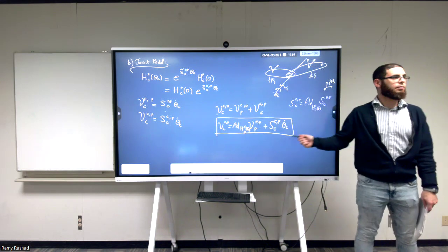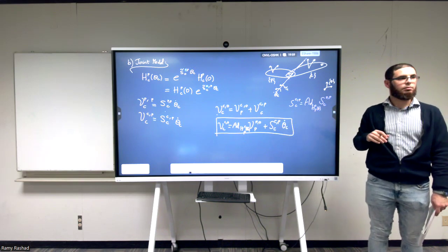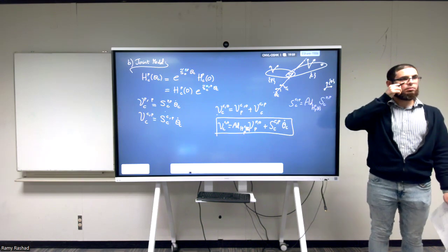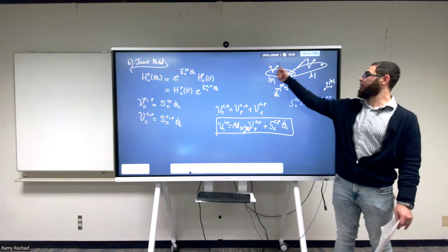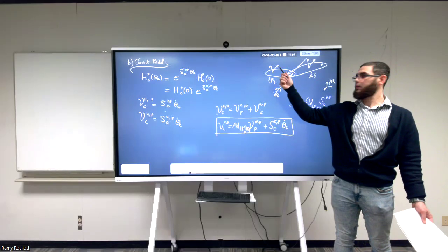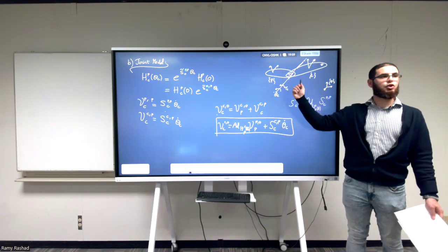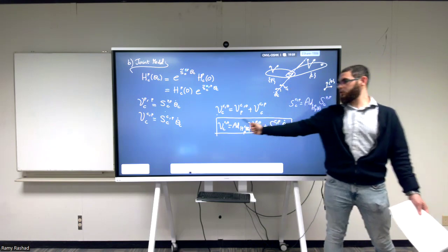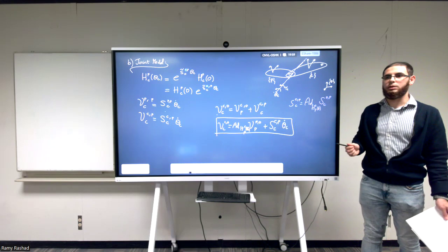What does this expression say? Okay, can someone read it and just try to figure out? It's a map that takes what and outputs what? It takes the generalized twist of this body. How many degrees of freedom does it have? 6. And it takes also on this side what? The angular velocity of the joint. How many degrees of freedom is that? 1. And what does it produce? VC with respect to 0 expressed in C, the child twist.